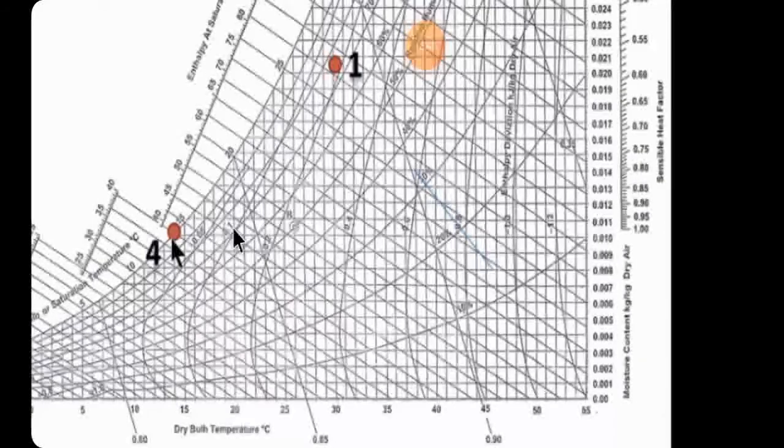You have to take the value at 15.6, not 14. That's why we take the value of enthalpy as 43. Don't take the value at 14, your answer will be wrong. Okay, you have to make a straight line and scan the page if the paper is online, and if it is in hard form, you have to submit the psychrometric chart as well. We will provide the psychrometric chart from the department.